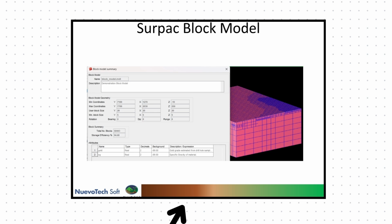Surpac's block model is defined in 3D space. We set the minimum and maximum coordinates, like northing, easting, and elevation. Each block is represented by its centroid coordinates, like y, x, z. All attributes for that block, like the ore grade and the density, are stored there. For example, at a gold mine, you might see each block's latitude, longitude, and elevation associated with a grams per ton value. Importantly, Surpac allows variable block size, but for most planning we use a fixed block size to simplify the calculation.